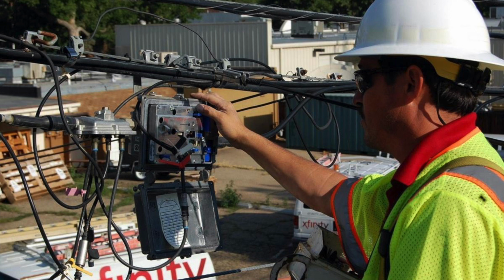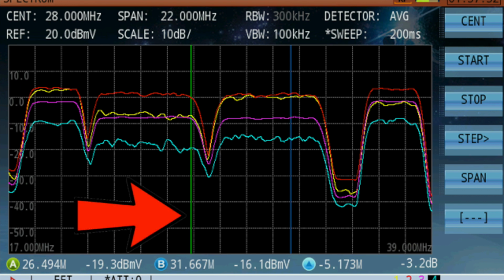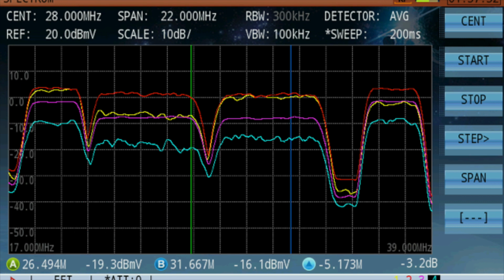If the field technician uses a typical RF sweeping spectrum analyzer, there are several ways to capture ingress and RF energy. Essentially, you have the ability to display simultaneously multiple traces differently processed through the spectrum analyzer's circuits, with min, max, average, and live traces. The sum of those accumulated traces don't typically give you the ability to see below the desired signal, essentially masking any undesired RF energy, as shown in the figure.